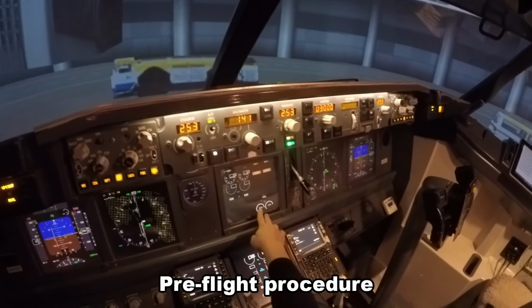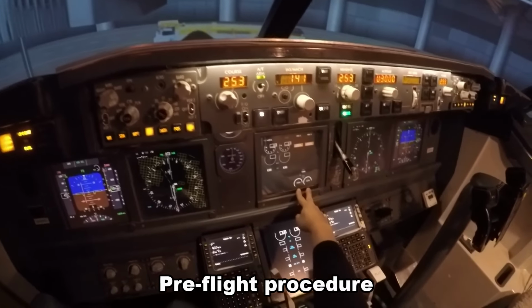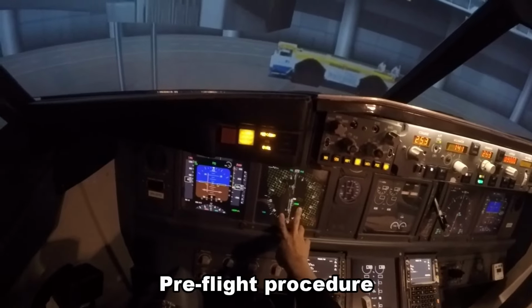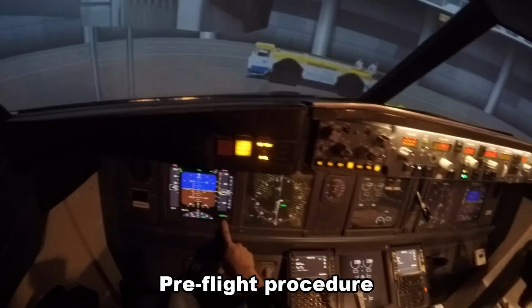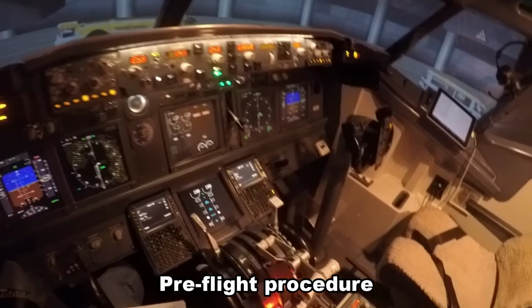And we'll just set our auto brakes to RTO. We've got 6.5 tons of fuel. Our nav display and PFDs are all set. We've got V speeds, heading is correct, altimeters are correct. Alright, so the next thing we'll just go to the throttle quadrants.